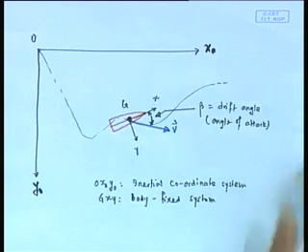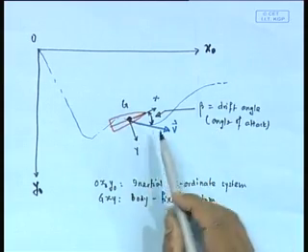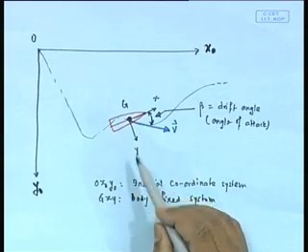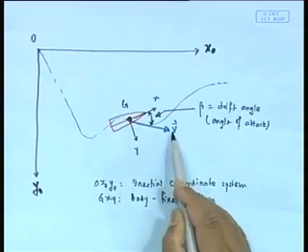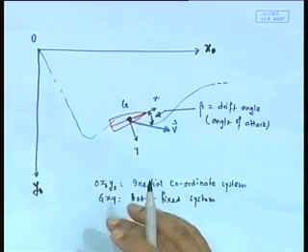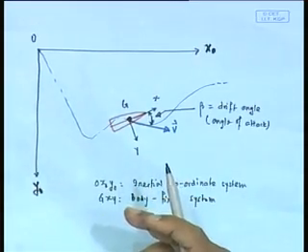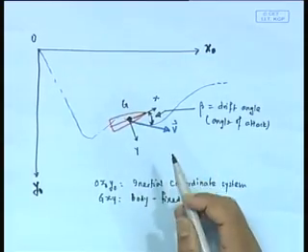Why I am saying this is that if you think of this ship as a lifting surface, which of course eventually behaves as a very low efficiency lifting surface, then this becomes my angle of attack. But typically in our nomenclature it is referred to as the drift angle.